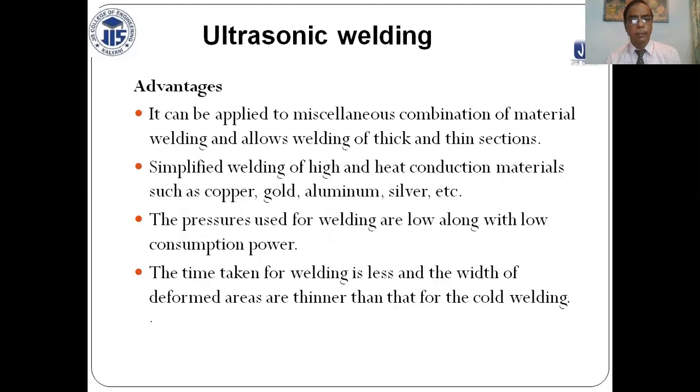Ultrasonic welding advantages: it can be applied to miscellaneous combinations of materials and allows welding of thick and thin sections. It simplifies welding of high heat conduction materials such as copper, gold, aluminum, silver, etc. The pressures used for welding are low, along with low consumption of power. The time taken for welding is less and the width of the deformed area is thinner than that for cold welding.